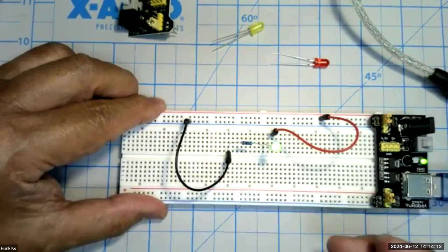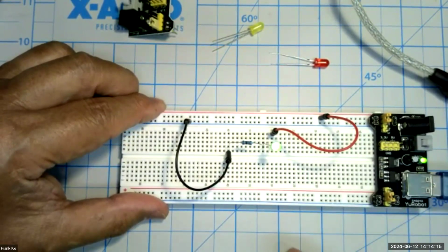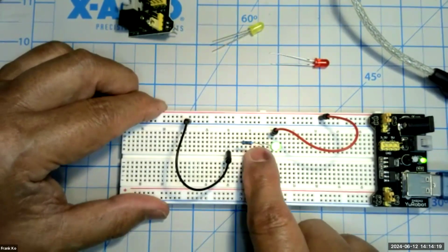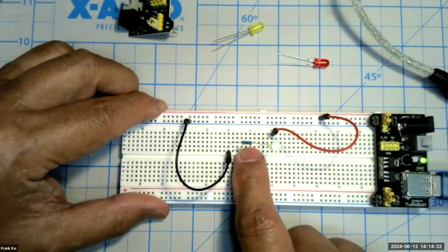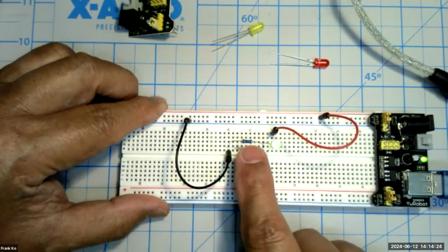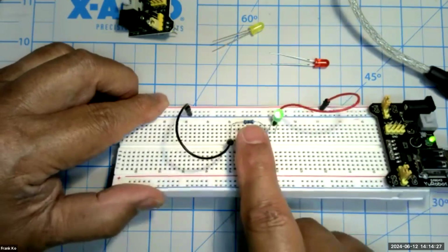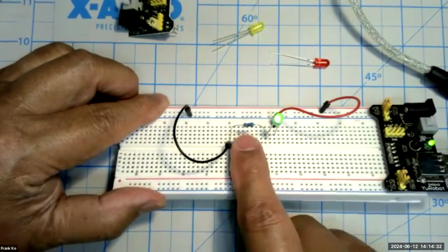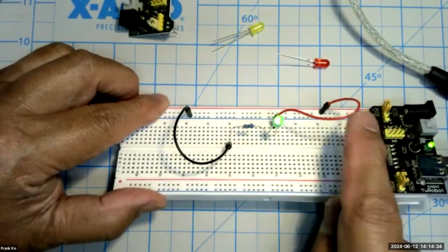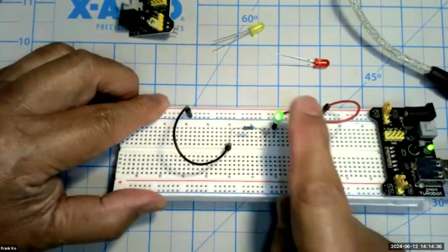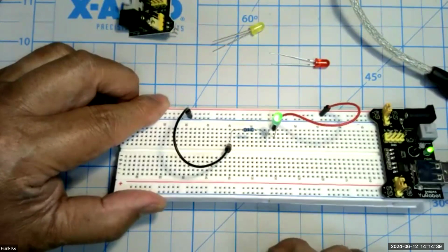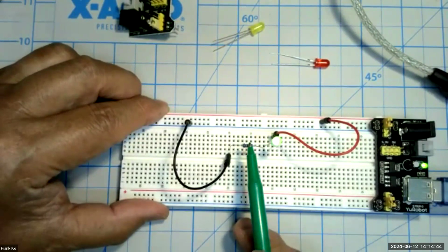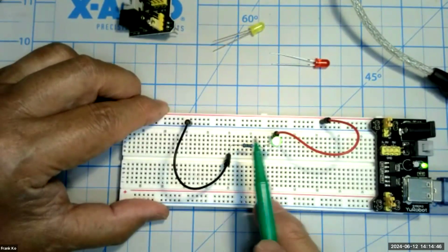Resistor resists. And I try never to use the word to define itself. So the resistor's job is to oppose the flow of electricity to a certain degree. The amount of resistance can vary depending upon the design of the resistor. So 100 ohms has some opposition to current. It will restrict the current to a certain amount depending upon other devices in the circuit. And used in this fashion, because of its function, it is called a current limiting resistor.